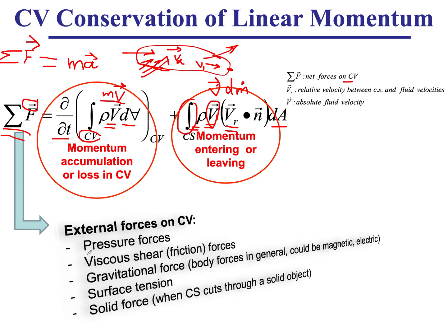One is pressure force. So that is when you're cutting through a fluid, just like we have done when we were dealing with a static fluid. When you expose the interfluid forces, or the force between a fluid and a surface, that most definitely is going to involve a pressure force. So that's your pressure force. And now that we don't have a static fluid, but rather a moving fluid, we can also expose the viscous shear forces. That's the frictional forces that exist between fluid elements themselves, or between a fluid element and a solid object.